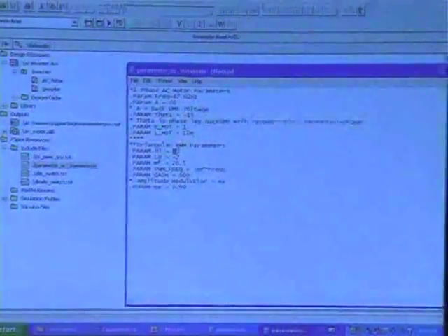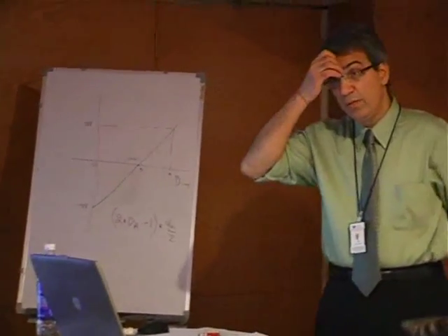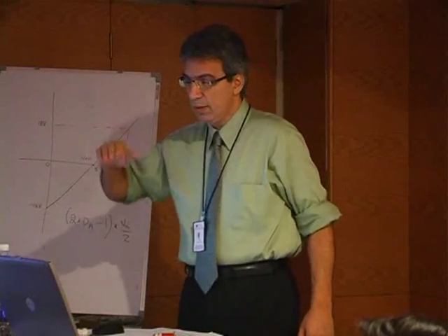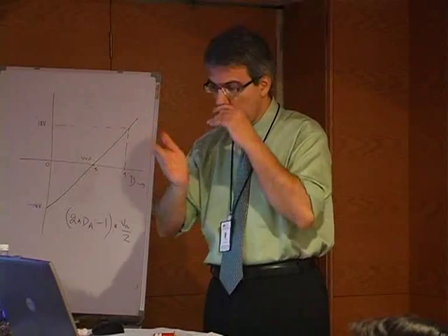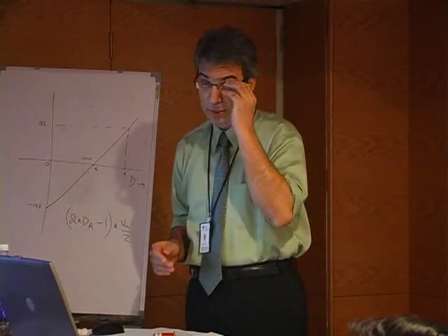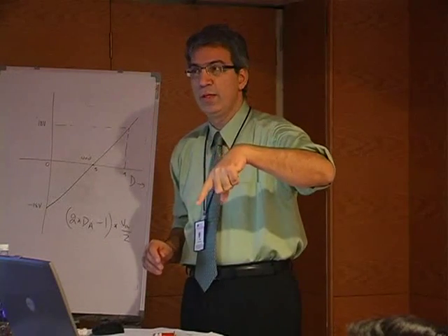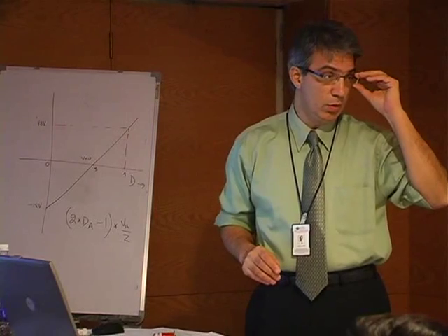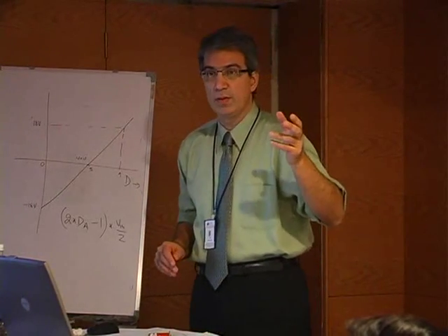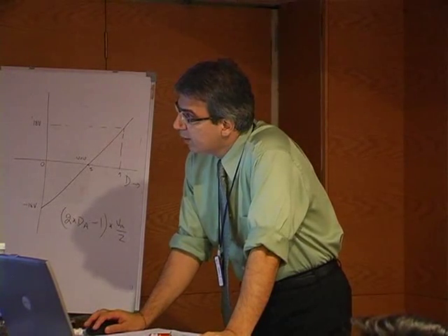One interesting thing we have done is change the high and low from +2 to -2. You only need 1 volt to turn on our switch, and we have made it from 2 to -2. This way we avoid having a delay because the transitions don't overlap too much. If you have high voltage, then transitions overlap. That way we can avoid a shoot through. If you have a shoot through in simulation, then the simulation is going to give you wrong results, right? So here, to avoid the shoot through, we have done 2 and -2.